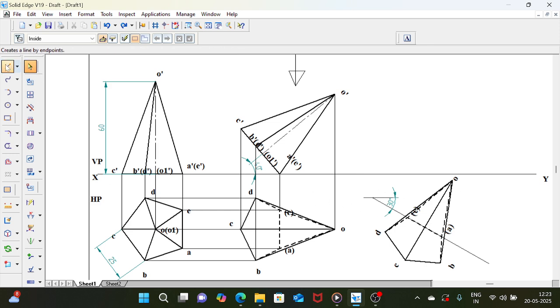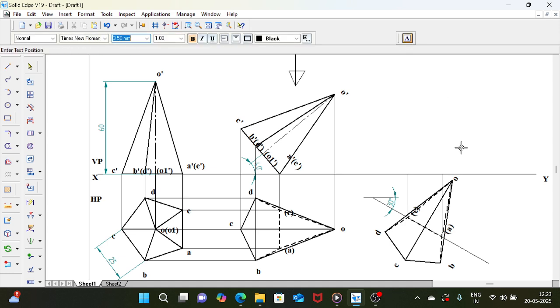Okay. So now I will take the projection line. See here, along the XY line AE projection is coming. I project AE up to the XY line, A up to X, E also up to X, and mark that as AE. Then and there itself, A dash. This is E dash.